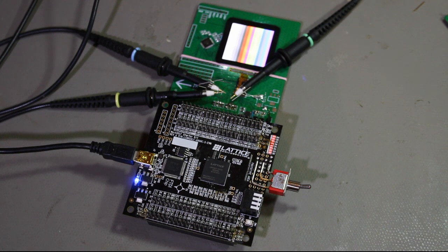There is already enough information available in the public domain about this particular iPod display. This is a single lane MIPI display, 240 by 240 pixels, 1.54 inch. As this is a MIPI display, communicating with it will be according to the MIPI specification. But MIPI is a closed standard, so in theory you will not be able to gain access to the MIPI specifications. But thanks to many other makers, MIPI specifications for DSI are available just a web search away.